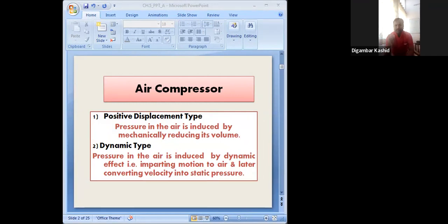In the pneumatic system, compressed air is required, and we get that compressed air from the compressor. In the compressor, atmospheric air is taken inside and compressed. But whether that compressed air is conditioned or processed or not, we should know. To condition or process that air, we should have a filter, regulator, lubricator, muffler, and air dryer. These elements are in every pneumatic system.